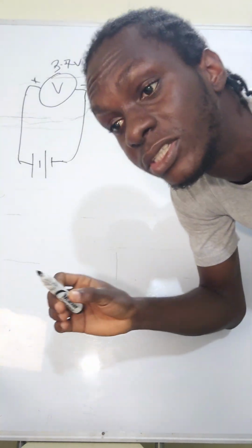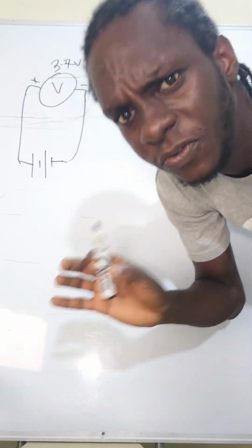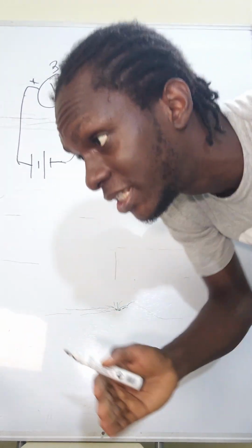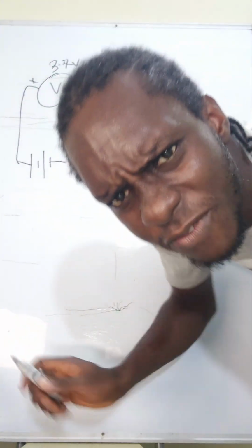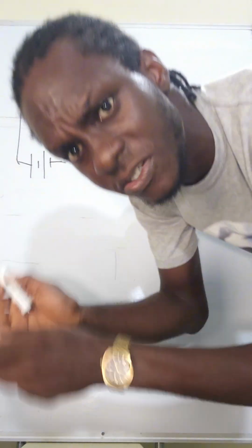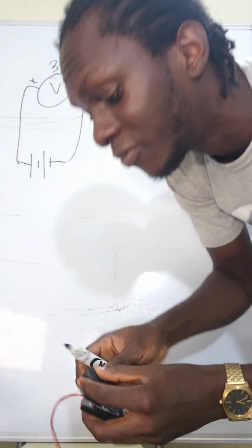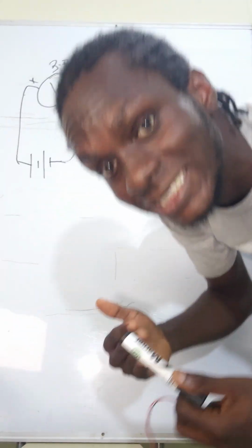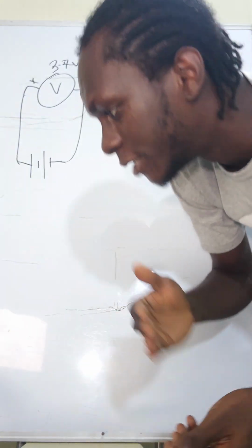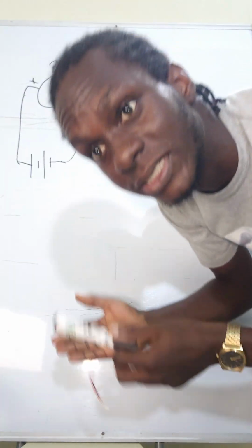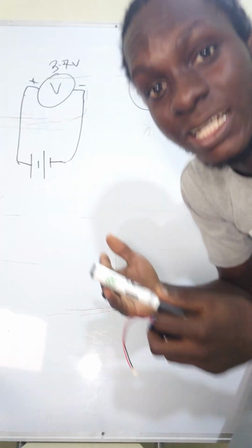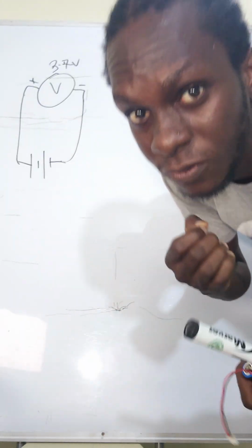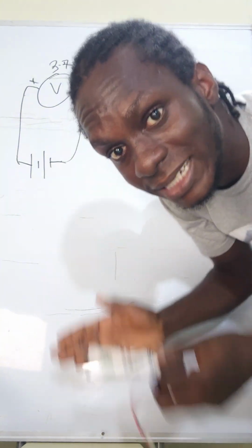Voltage, even if the circuit is open, voltage is present, but for current it is what you are demanding that you are getting. Voltage is available every time. When you come, you see voltage, but for current you have to demand it, and it is the amount of current you demand that will flow towards what is demanding it. And that's where, if the cable is not sized appropriately, when you are demanding much current, the cable will start heating up because it is not able to carry the amount of current you are demanding through that circuit.